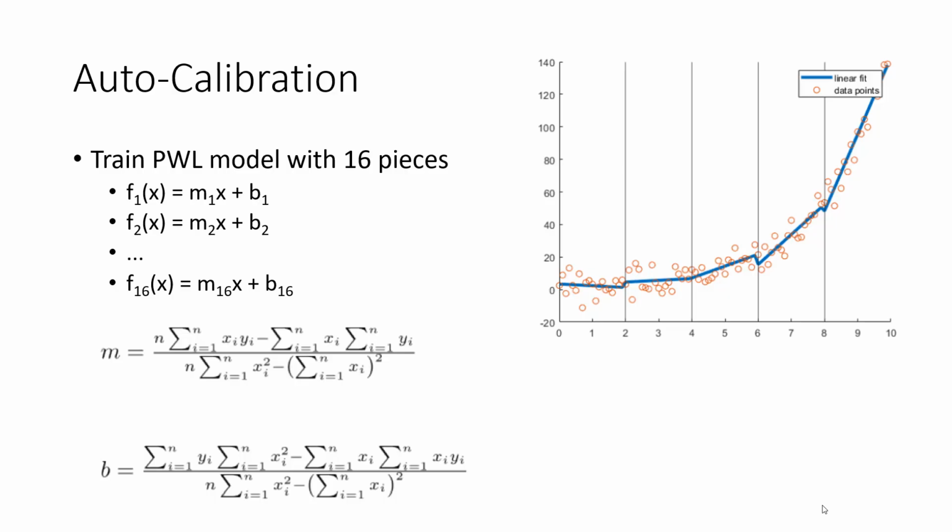What is X? X is the input from the ADC, and Y is the ground truth value that the scope is set for. The idea is that we're correcting the ADC. So when this is done, you read from the ADC, that's your X, you plug it into the model, and it gives you Y, or f of X, which is the corrected form.